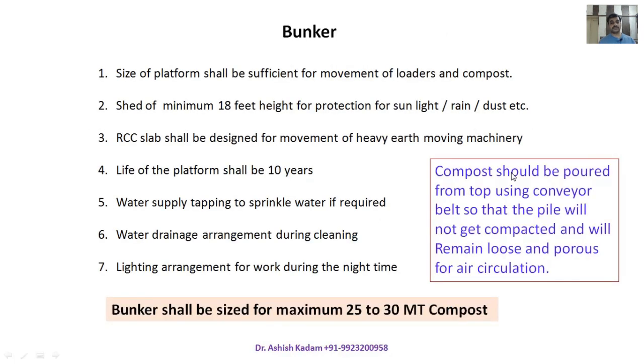Next is the bunker. Once you make the compost on the turning platforms, then we shift it for further maturation of the compost in the bunkers. In the bunkers we supply the air from the bottom, that we have seen in video number 2, and how to design the bunker, etc., we have seen. But these are some of the important considerations which we are again discussing here.